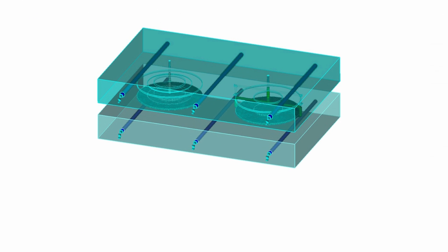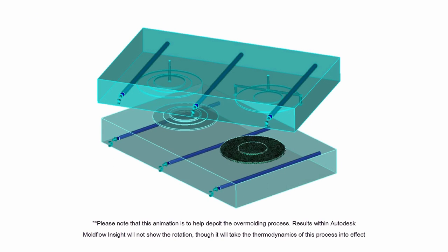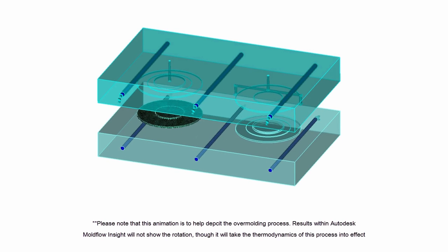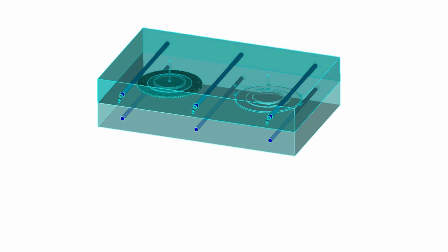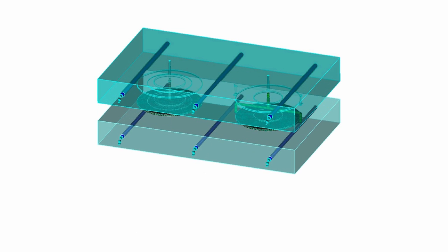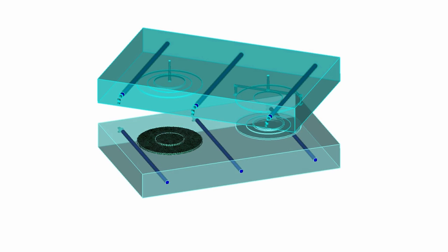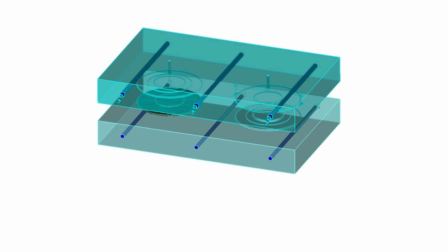In the overmolding process, the mold plate rotates after the first shot or substrate is done and carries the part over to the second shot position, where the second shot is molded over the first shot. This occurs simultaneously as another substrate is being molded. The rotary motion allows for a continuous two-shot manufacturing operation.